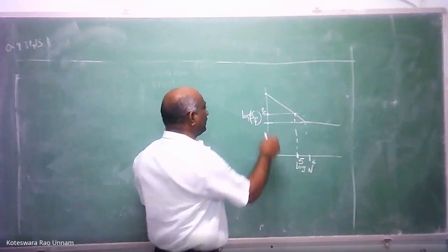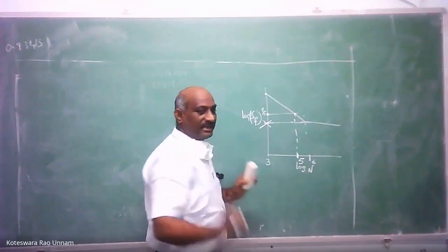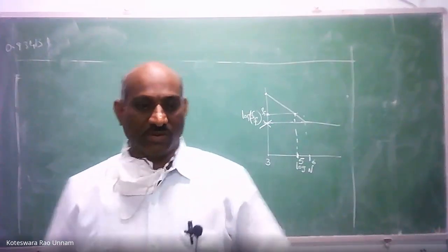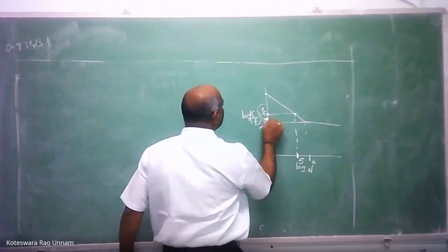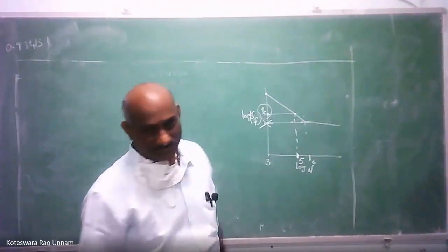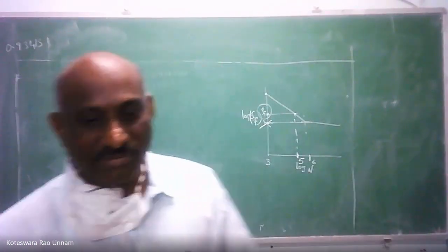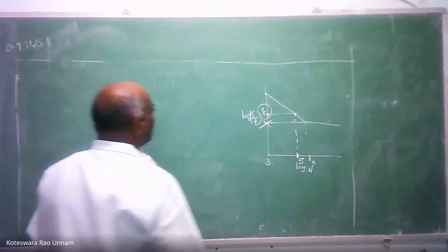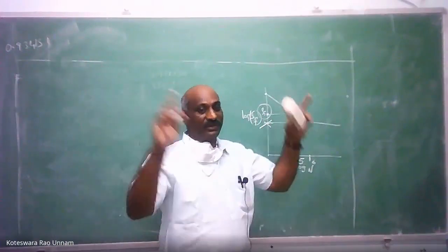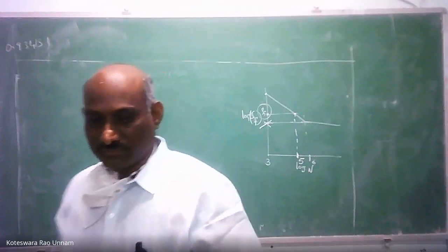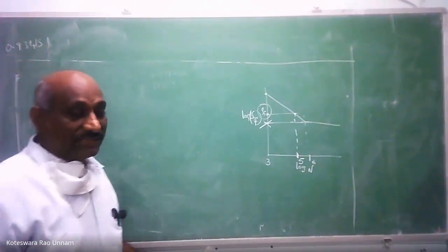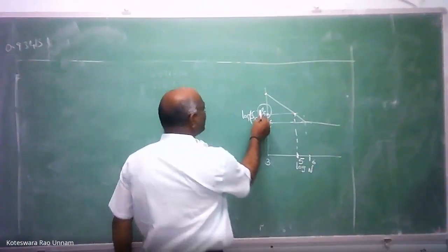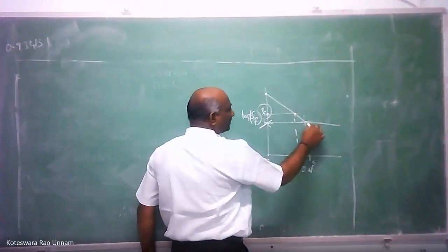So that means your SE is not the design criterion now. You need to first estimate what SF is. Then based on that SF only can you design the component. But to estimate this SF, you need to have this failure curve equation.